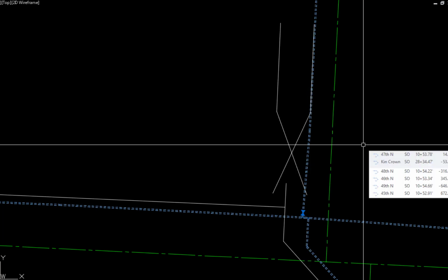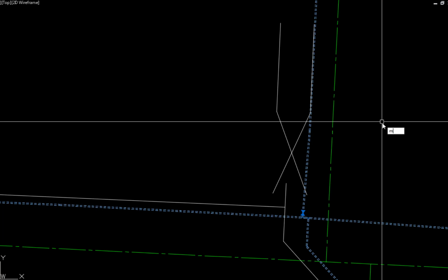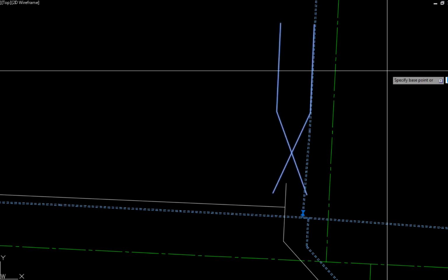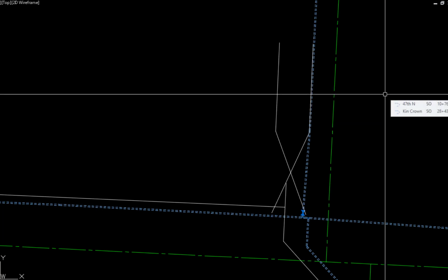Enter, enter. Move the template along the existing pipe until an angle line intersects the new pipe at the desired bend location. Move, enter, pick the template, escape. Repeat at other locations where the new water pipe is to join existing.